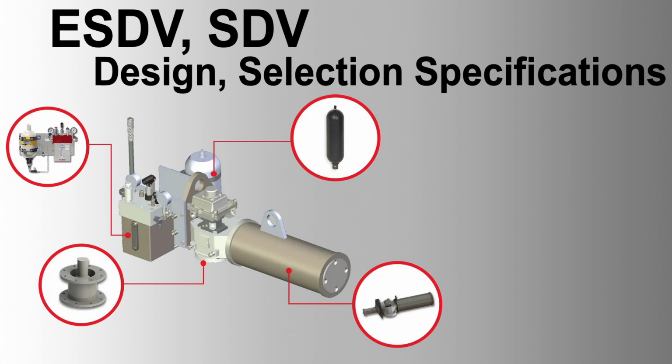Actuator valve interface, mechanical compatibility: must ensure the actuator is fully compatible with the valve regarding torque, thrust figures, and mechanical stresses. Support brackets: additional support brackets must be designed to support the actuator's weight on the valve body. Secure assembly: the assembly mounting must be capable of withstanding stresses from valve and actuator movement.